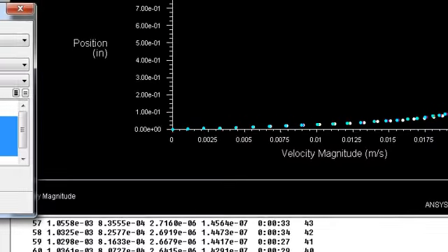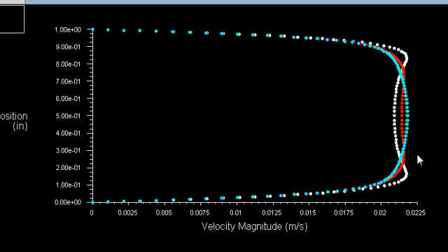We can easily observe here also at 1 inch apart the velocity is the white one, and at 2 inch apart the velocity is the red one. So it still is in developing velocity, but at 3 inch it's getting more parabolic.